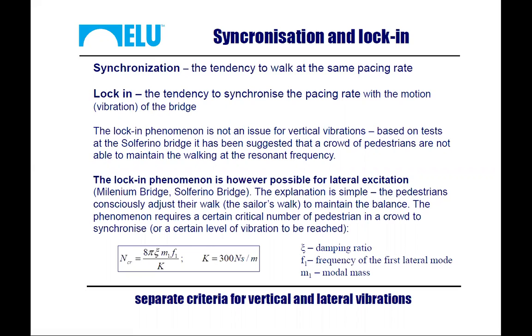However, lock-in is possible for lateral excitations. And the explanation is very simple. Once the bridge starts to move, in order for the people not to lose their balance, they will adjust their walk to the motion of the bridge.